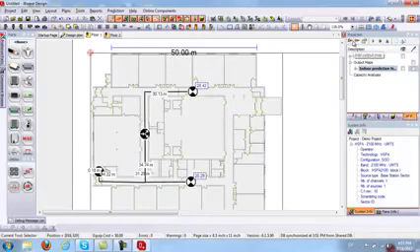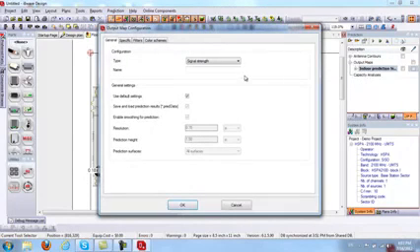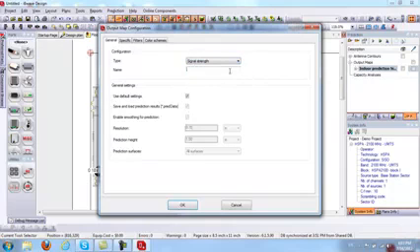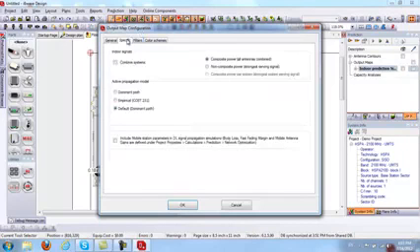And from here, I can add the different output maps if I click on the plus button. Under configuration, you can display or choose the type of configuration you want. So I'm going to do signal strength. I can give it a name here, signal strength map. Under specific, here this is where you can set your propagation model, dominant path or cost empirical 231. Dominant path is set by default, so I can keep it there by default.